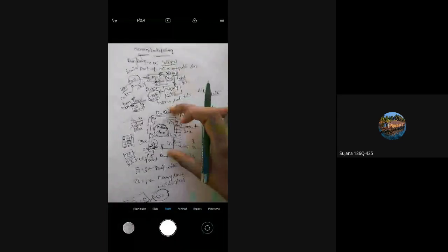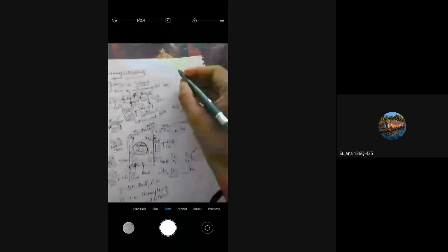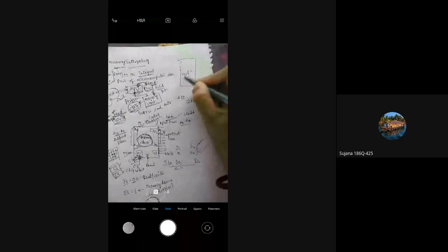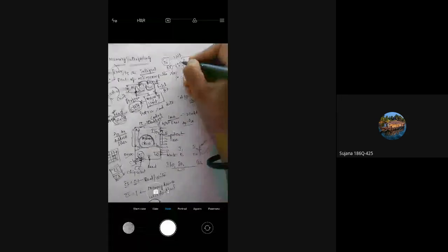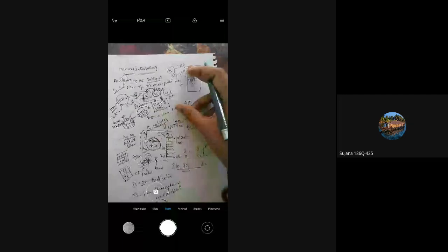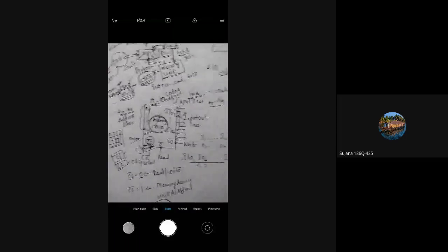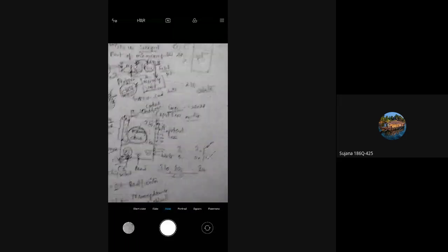So this is the memory device unit, and you all know the microprocessor is a 40 pin device. Okay, so it is a 40 pin IC. You have 20 address lines and 16 data lines, which are multiplexed up to 16 address data lines, and the remaining 4 are only address lines. So these will be connected with these lines, and on chip select activation, the transferring of data will be done and the operations will be performed.